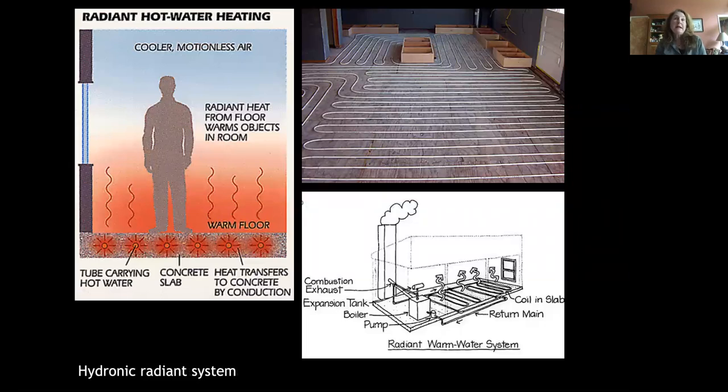So while radiant heat is great, electric resistance heating, the way he used, is really expensive. So the more common systems are to use hydronic water systems as your radiant systems. And this was tricky some years ago when pipes would corrode and break and cause people a lot of concern. But now they use this continuous plastic tubing called PEX. It's very flexible. It's really durable under temperature extremes. And it's installed as a continuous loop so that there's no place to leak. And there really hasn't been any problems with this system.